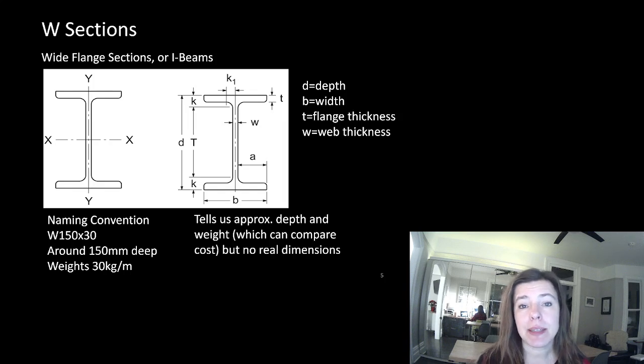And the reason that's important is, remember, everything we're trying to do is build the cheapest building we can within our constraints. For steel and most materials, you can judge which one's more expensive by which is the heavier one. So the lighter it is, the less it weighs. The heavier it is, the more it weighs. There is cost and complication and piece count, but normally it comes down to weight.